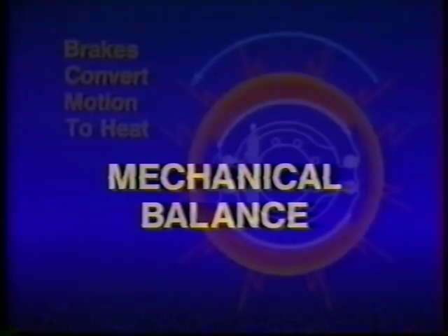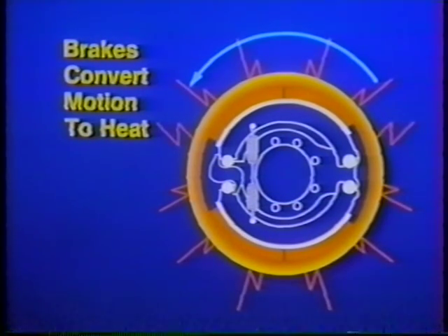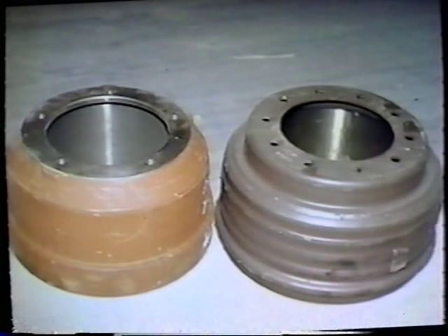But even when pneumatic and torque balance have been achieved, mechanical factors can throw the brake system out of balance. Basically, mechanical balance concerns how brake systems handle heat. Brake blocks and drums stop a vehicle by converting motion energy into heat. The heat generated is transferred into the drums and ultimately dissipated into the air. Obviously, the amount of heat that different types of drums can store and dissipate is an important factor.